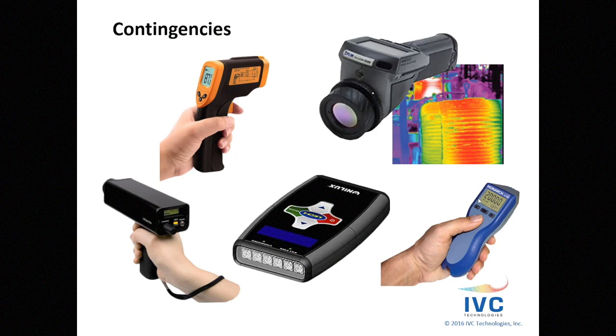And then we had mentioned previously contingencies. Sometimes you may get out to the field and you're getting ready to do vibration testing and realize vibration isn't the parameter I should be looking for. It may be temperature, it may be ultrasonics. I may want to actually pull out a strobe light to freeze the shaft and see if I have the shaft oscillating or if it looks like the key is bouncing around in the keyway while it's turning. This is what I mean by having contingency plans.